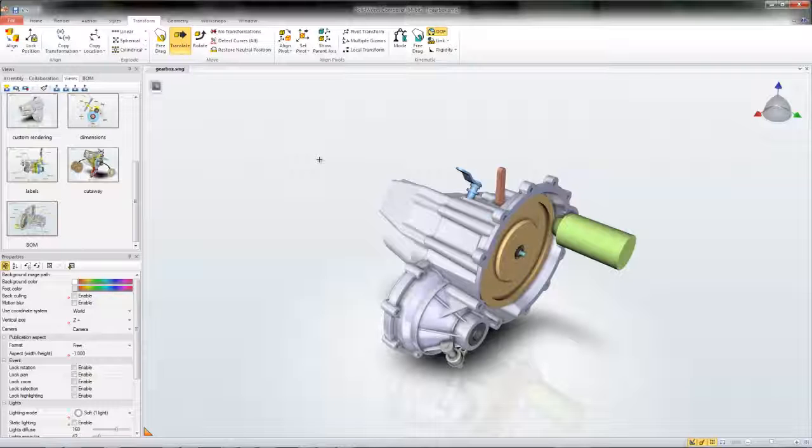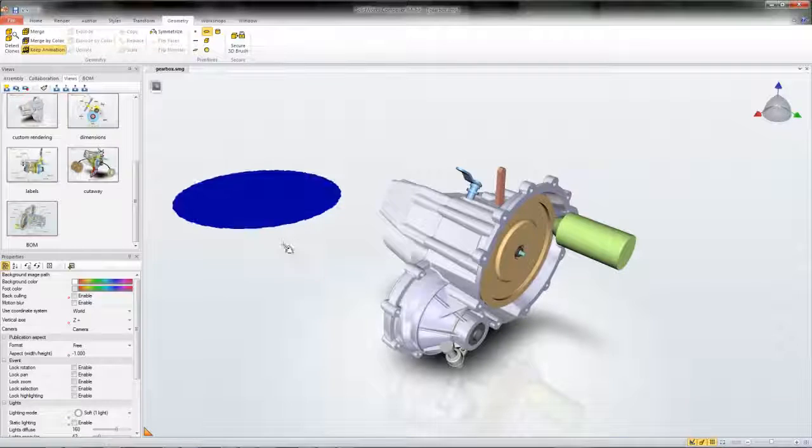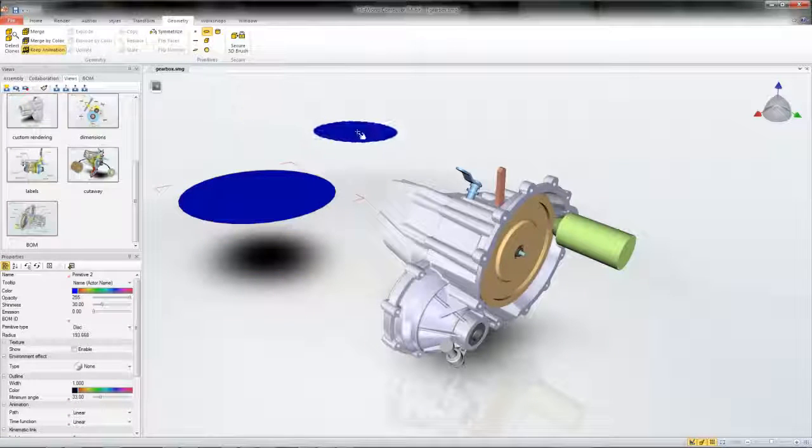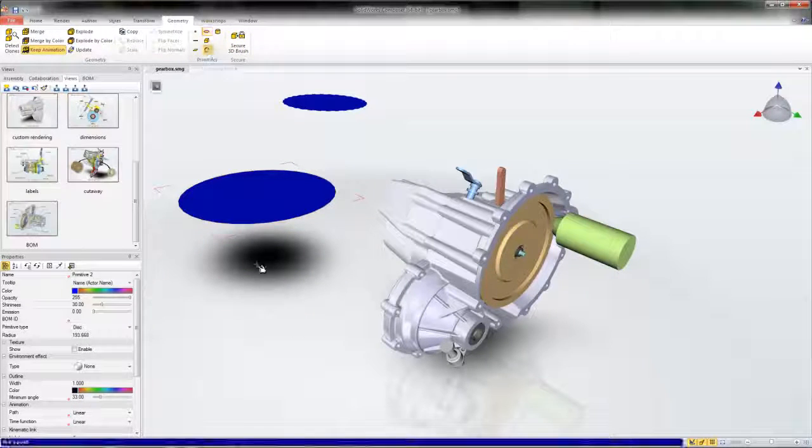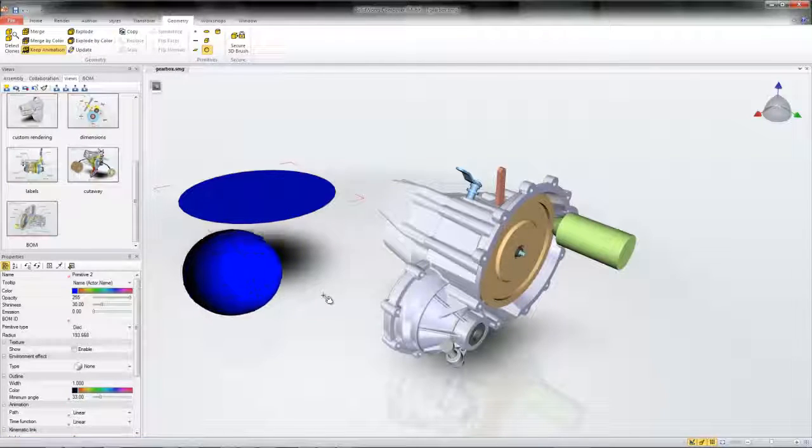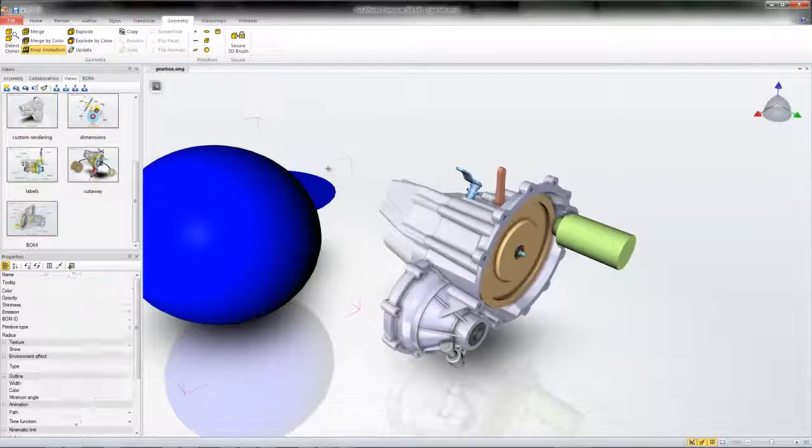On the right side, you'll find the Pivot and Kinematic tools. These can be used to create kinematic joints and relationships which will add increased intelligence to your Composer assembly. See the video about kinematic tools on our YouTube channel. The Geometry tab contains various advanced tools you can use to modify actors' physical geometry, as well as create different primitive pieces of geometry like spheres and cylinders.